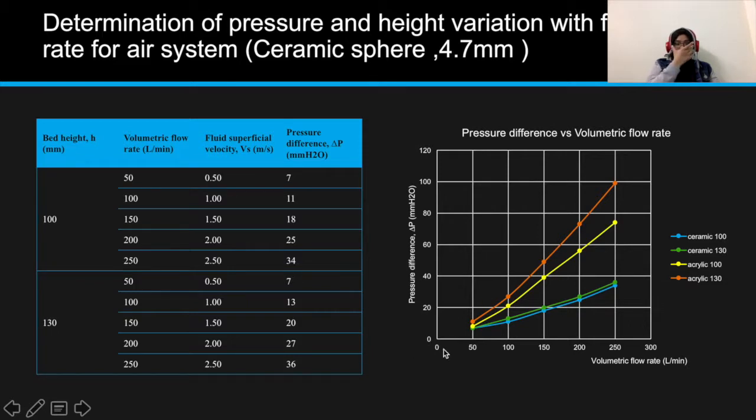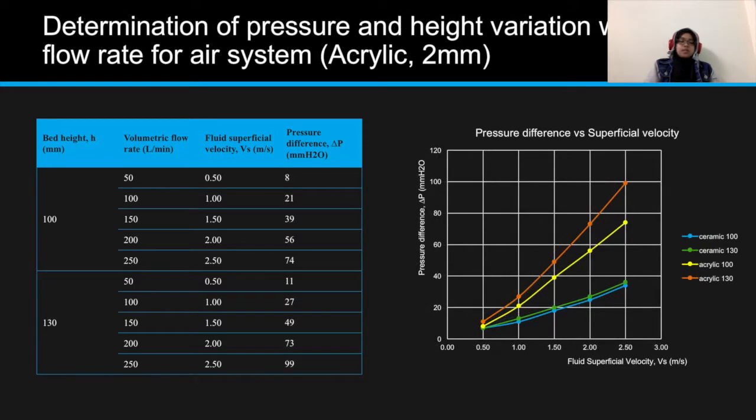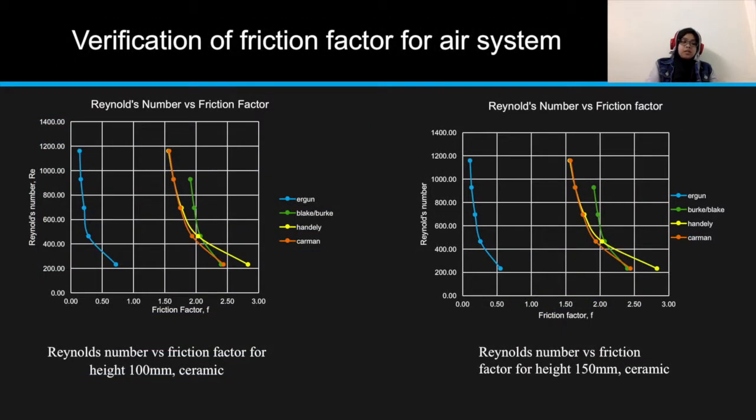Bismillahirrahmanirrahim. My name is Marsha binti Muhammad Najib, and I'll proceed with the results and also the discussion part. As you can see, this is the variation of pressure and height with the flow rate for air system, for ceramic sphere and also the acrylic. So the bed height does not change the behavior of fluidization. The significant difference is only shown by the ceramic particles with the difference of height, but not the acrylic particles.